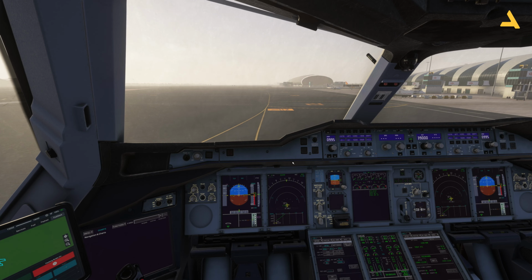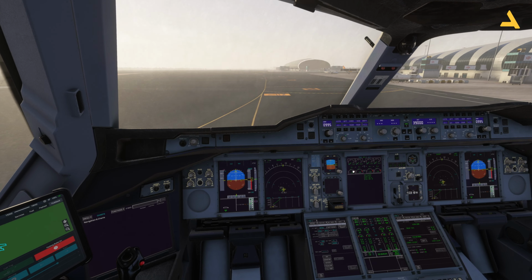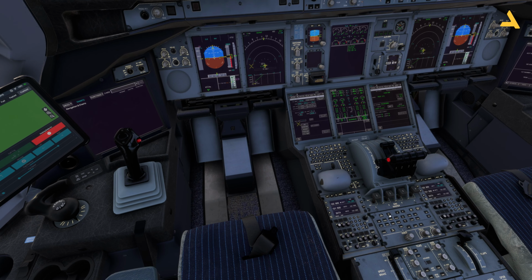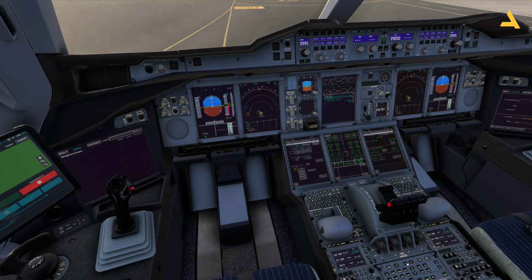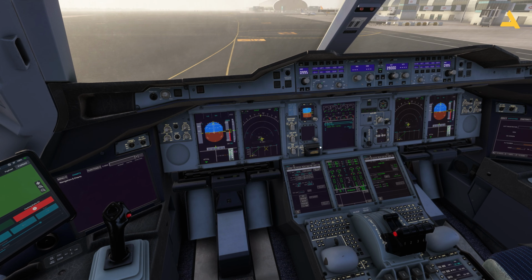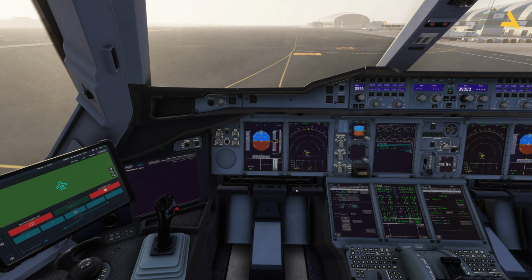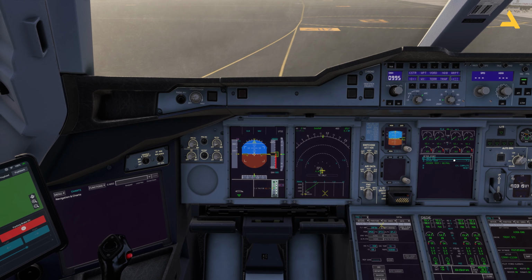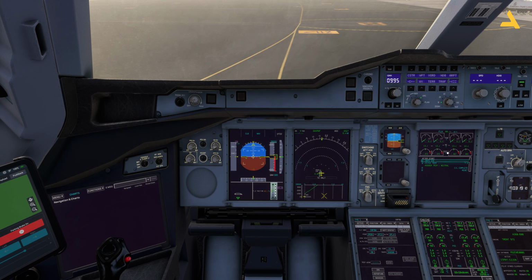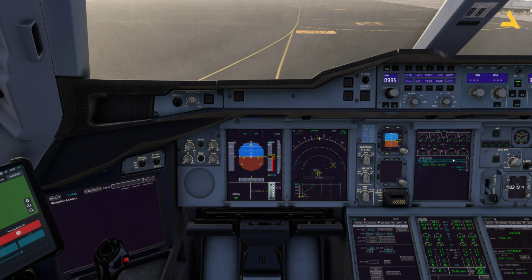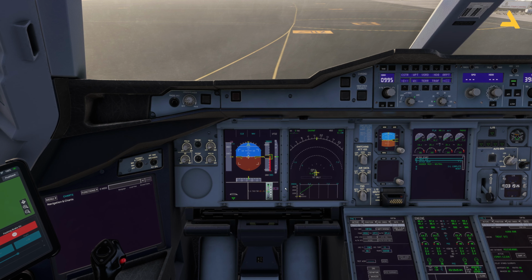So now everything is good. Let's bring up this checklist. Press this stick and let's keep this thing over here. Right now, as the engines are not running, the power from the engine is not available. That's why the hydraulic system is not working. But as soon as the engines are available and you have power from the engines, then the hydraulic system will also work, and you will see the trim is getting set for the takeoff.